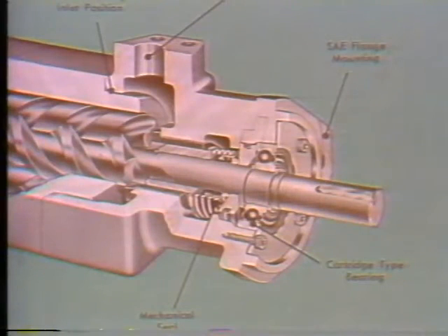An assembly print may often omit dimensions or materials because the point of an assembly print is to show how the parts of the machine fit together and what holds them together. A cutaway is used to clarify a piece of equipment or how a part operates. Remember that a pictorial drawing is often used this way to complement a symbolic representation.